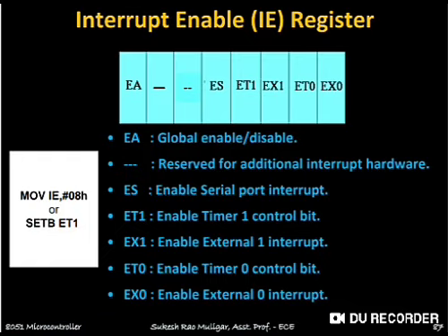that is external interrupt. So there are 6 interrupts including reset, so totally 5 interrupts, and for all the 5 interrupts you can find the bits. When you set a bit, that interrupt is enabled. When you reset it, it is disabled.